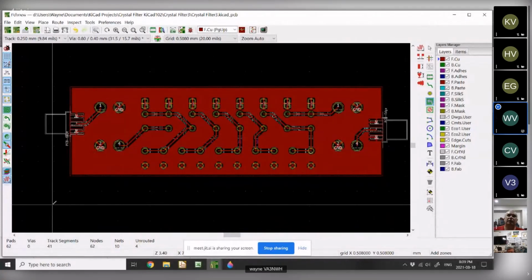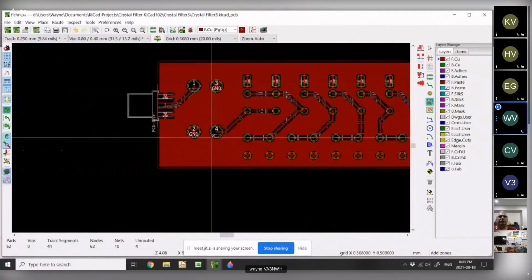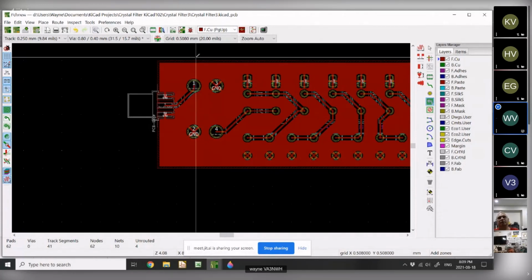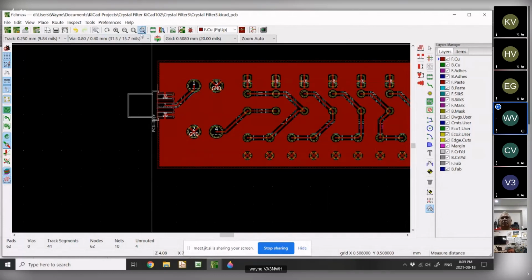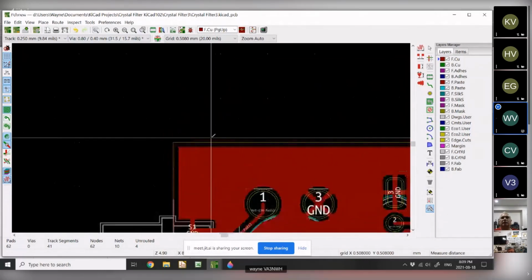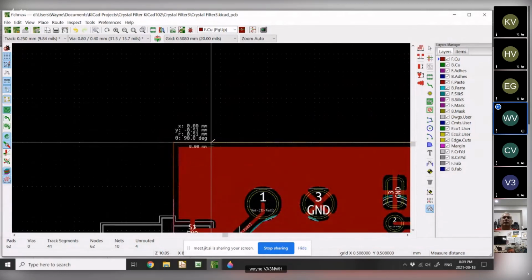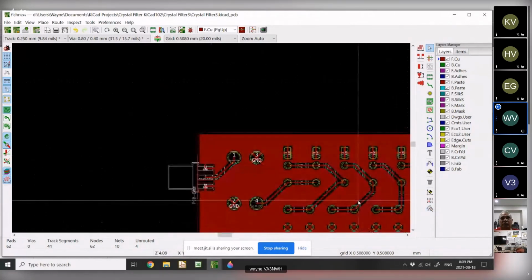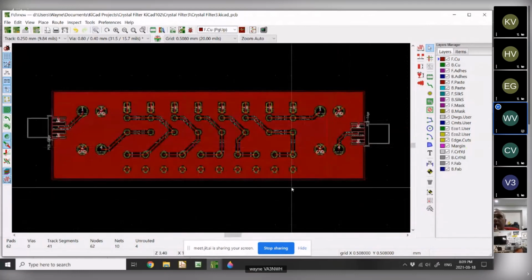Now it's done the fill on the front, and I will point out that it has left a zone. This is for a reason that I've forgotten, but it will not fill to the brim for you. Don't worry about it. Unless, seriously, if you actually want the copper to come to the edge, you've got to start outside. That's hard, but you can measure it. The measure tool, which I'm clicking now, I'll bring this big enough to actually see, tells me that's 50.51 millimeters, in case that matters to you. Okay, and that's a default. Back home again.